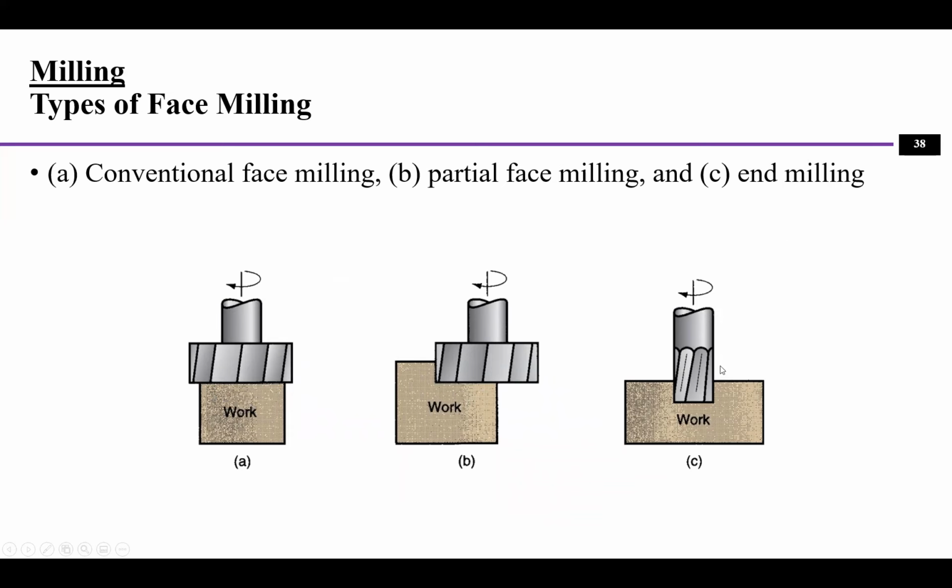End milling typically gives us more flexibility in machining the different geometries of the products, because the tool can move here and there and up and down without destroying material from other places. Like this, if the tool is too big, the flexibility of the geometry is a lot lower. But end milling overcomes that difficulty and gives you a lot more flexibility in making geometries.